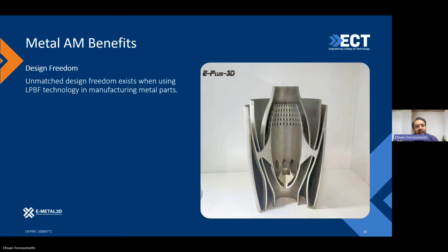Maybe we are not really in the aerospace industry, or maybe you're not really dealing with carbon footprint, but definitely as a designer, freedom in design is crucial. You know that if you want to make something complex, as this image shows, if you don't use additive manufacturing, how difficult it is to design such a thing. First of all, some features cannot really be manufactured, and you have to have a lot of components and a lot of procedures to make individual parts and then carefully machine them and assemble them so that you can get something similar to this. And that would definitely take a lot of time.